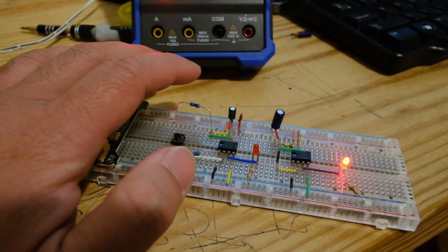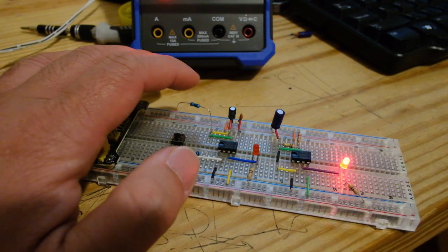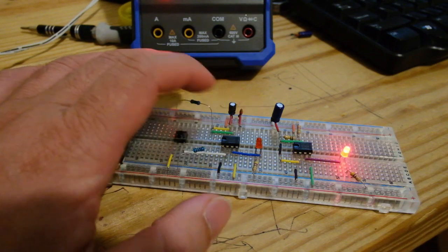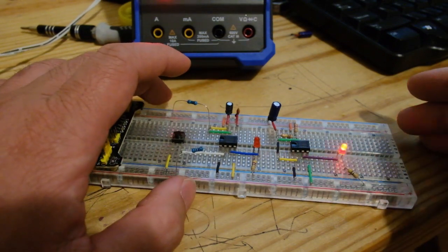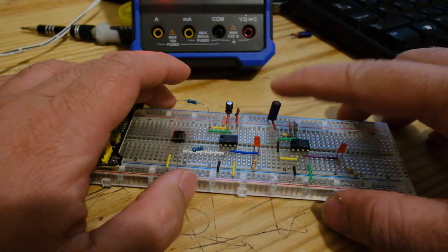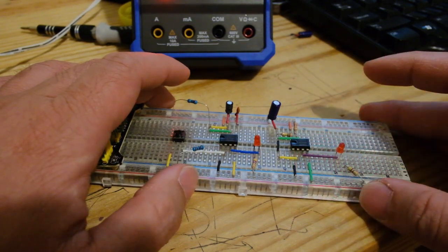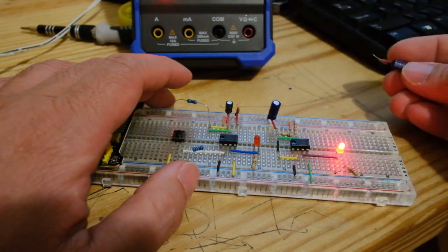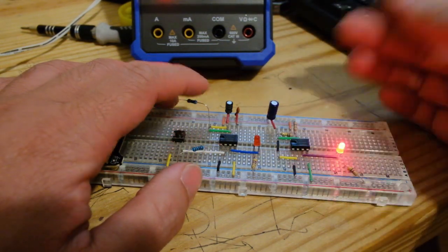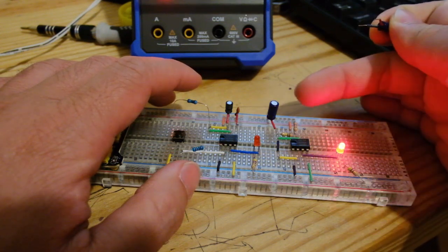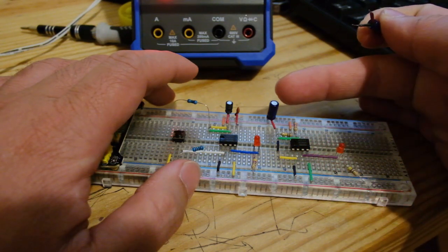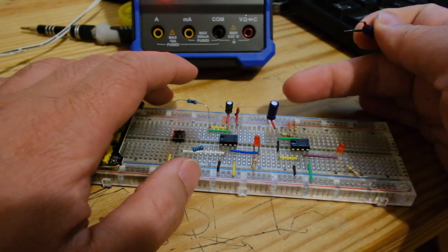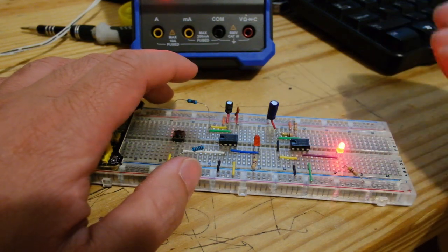Moving on to our second experiment, we will explore the astable circuit configuration while continuing to incorporate LEDs. Similar to the monostable circuit, we will use resistors and capacitors to control the timing, but this time we will generate a continuous output signal with a specific frequency. By adjusting the values of these components, we can precisely control the frequency and duty cycle of the output waveform. As we witness the LEDs flashing on and off, we can understand the practical applications of the astable circuit, such as oscillators, timers, and even flashing LED circuits.